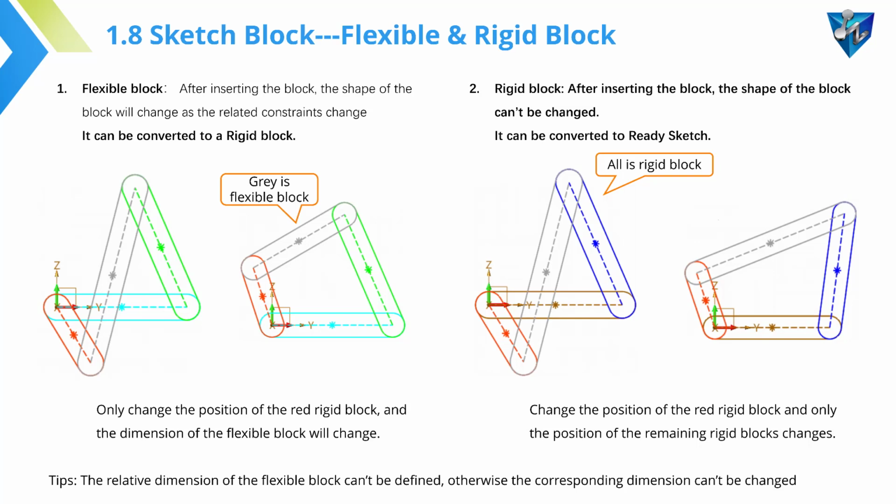And some tips for the flexible block. The relative dimensions of the flexible block cannot be defined. Otherwise, the corresponding dimensions can't be changed. Alright, let's move to ZW3D to show you an example.